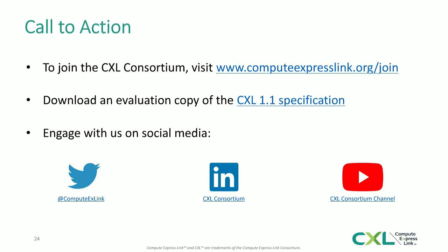Will latency time crossing the PCIe bus be reduced? Thinking about low latency requirements in HPC or HFT. I'm not sure if the question is about PCIe or CXL. For CXL, by making the flits and having different channels to send those flits over, you can achieve low latency. But PCIe is not the topic that we're discussing here, so I'm not sure whether the question meant CXL or something else.